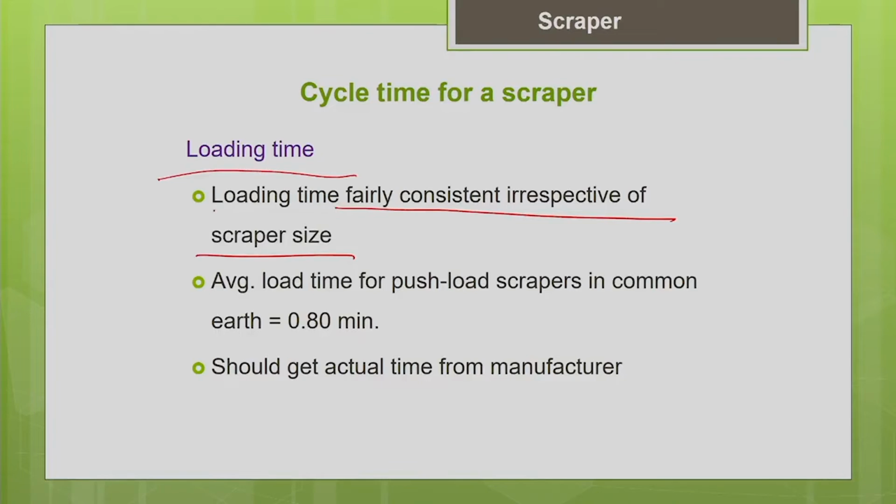According to the size of the scraper, you have to select the compatible size of pusher, and we supplement the loading power. That is why the loading time is fairly consistent irrespective of the scraper size. Since it is assisted with the pusher, the loading time won't change much.